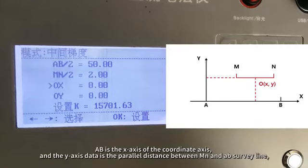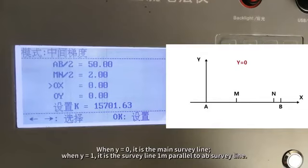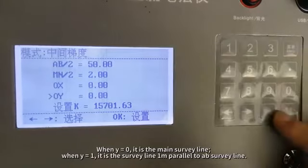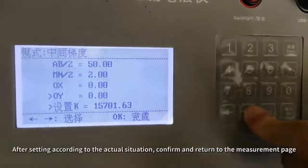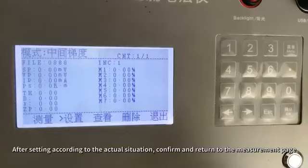AB is the x-axis of the coordinate axis, and the y-axis data is the parallel distance between MN and AB survey line. When y equals 0, it is the main survey line. When y equals 1, it is the survey line 1M parallel to AB survey line. After setting according to the actual situation, confirm and return to the measurement page.